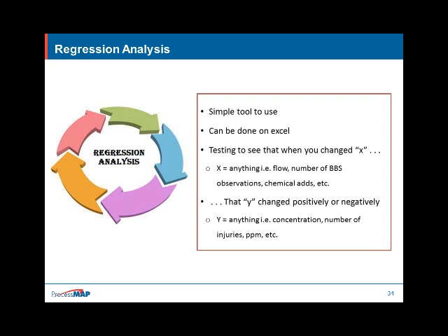3 months later, we had another exceedance. At that point in time, I blew my lid and I said, let me see the data. I did a regression analysis, and guess what? There was no correlation at all between flow and the data. What happened is that the underground sewer pipes haven't been cleaned out in decades. There was copper buildup in it. Somebody was using a cleaner that was slightly acidic, dissolved some of that copper, and sent it down the pipe.